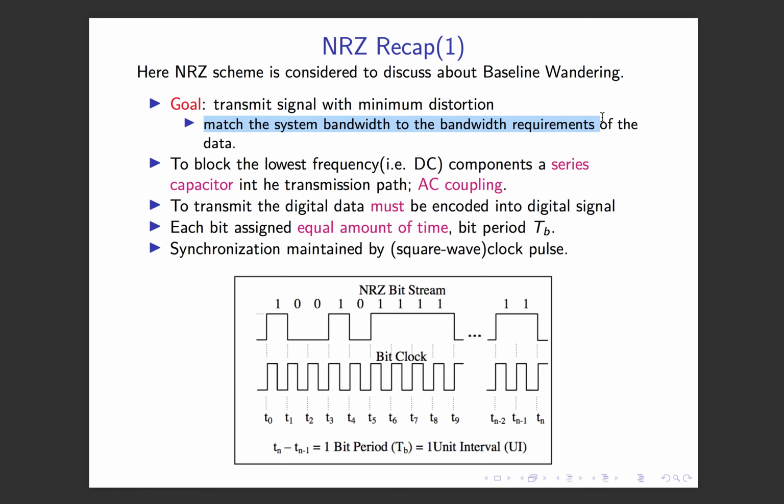Okay, so in a couple of minutes we will see what is the exact circuitry mostly used, or what is the basic circuit structure we use. Here we use AC coupling. A series capacitor is used to chop off the lowest frequencies, so that is the DC blocking capacitor.